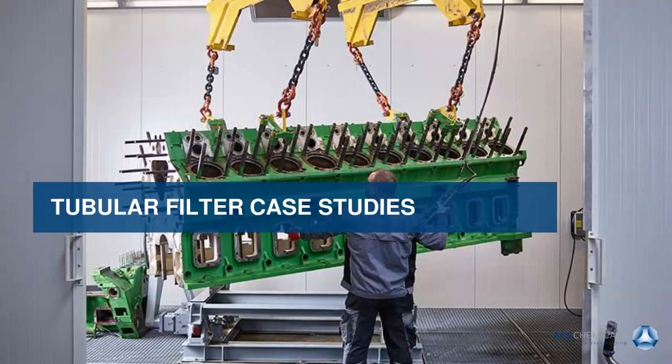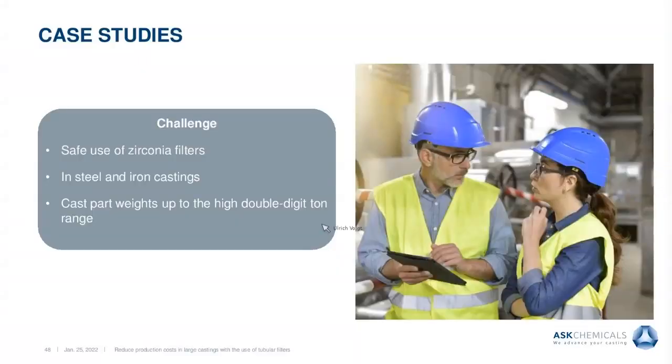Yeah, we should now switch over to some case studies. I think it's also of real interest for the foundry guys, for the practice guys, for you. Before we start, I would say that tubular filters for foundry casting are currently used on an industrial scale, and more than 1,000 tons of molten metal are poured through these filters per month. Foundries use these filters on a monthly basis to produce single castings between 2 and 33 tons each.